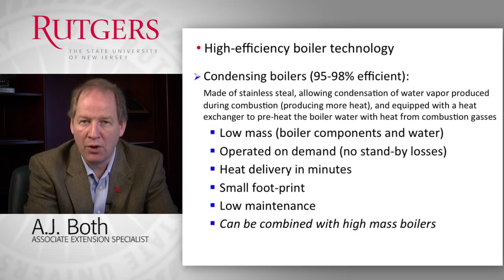So what this condensing boiler does is it condenses the water vapor that was generated by the combustion process. It condenses it back down to water and extracts, because that process of condensation creates energy, it extracts that energy and uses it typically to preheat the water that is being introduced into the boiler system before it actually is heated by the combustion process. So by condensing that water vapor in the combustion stream, we are able to significantly increase the overall efficiency of the combustion process, and of course that helps save energy.